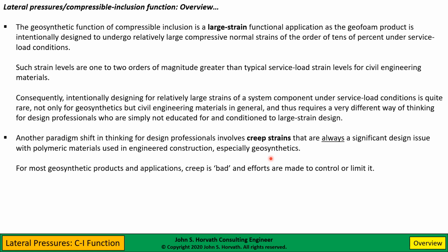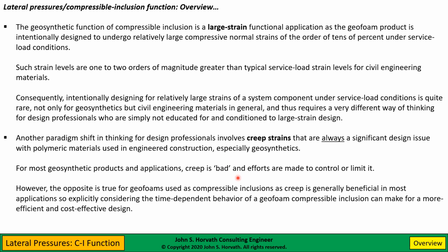And again, for relatively small strain applications such as mechanically stabilized earth walls, it's understandable that you want to limit the magnitude of creep for the geosynthetic tensile reinforcement. However, when we use geofoam as a compressible inclusion, creep is good, if you will. It's generally beneficial in most applications, and we should explicitly consider it.